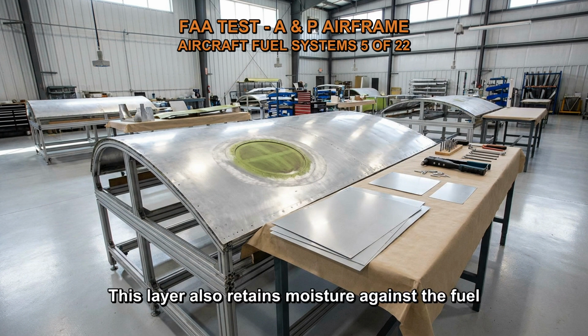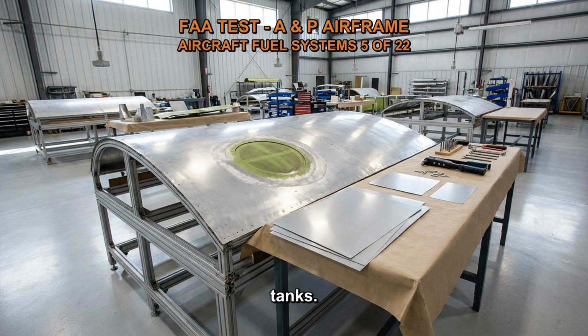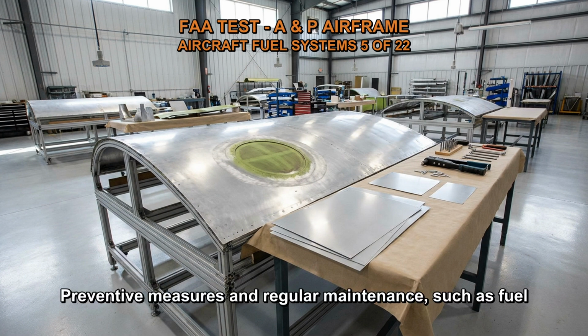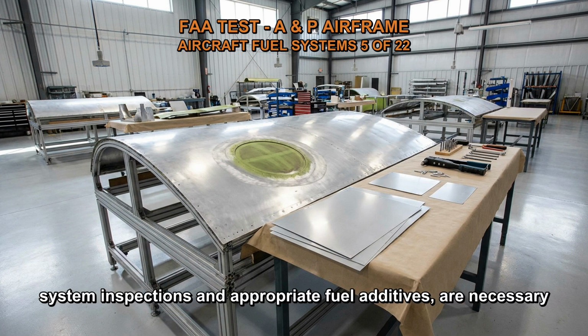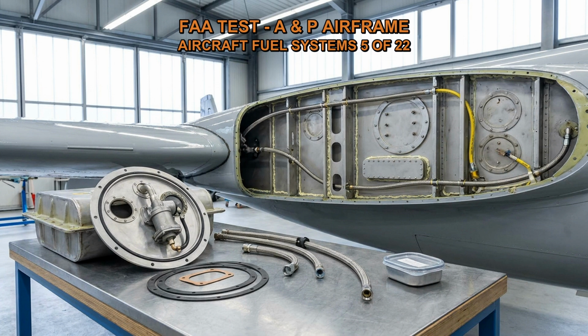This layer also retains moisture against the fuel tank structure, leading to the corrosion of the tanks. Preventive measures and regular maintenance, such as fuel system inspections and appropriate fuel additives, are necessary to mitigate the risk of microbial contamination and its associated problems.